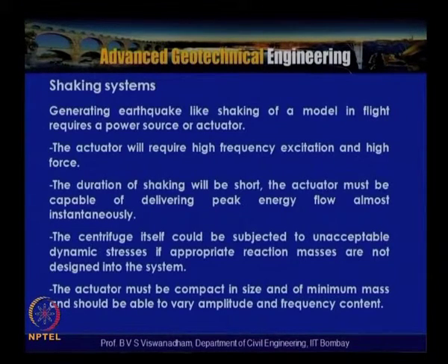First of all, let us discuss what the different shaking systems are, and then we will discuss why a laminar container is required. In order to have earthquake shaking, a number of ways have been tried. Generally, earthquake-like shaking of a model in flight requires a power source or actuator. The actuator requires high frequency excitation and high forces need to be applied, and the duration of shaking will be very short because the frequency is n times that in the prototype, so the duration is short, and the actuator must be capable.